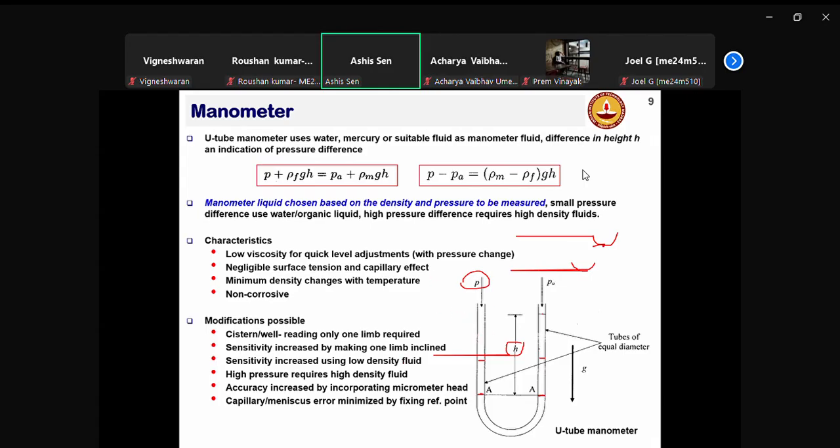I mean, the orientation of the U-tube and so on. If you put the U-tube like this, you have to make sure that this low density fluid doesn't rise. But if you flip it 180 degrees, then you can use this as a low density and this as a high density. So it depends on the orientation, depends on the pressure and so on. There is no unique answer to your question.